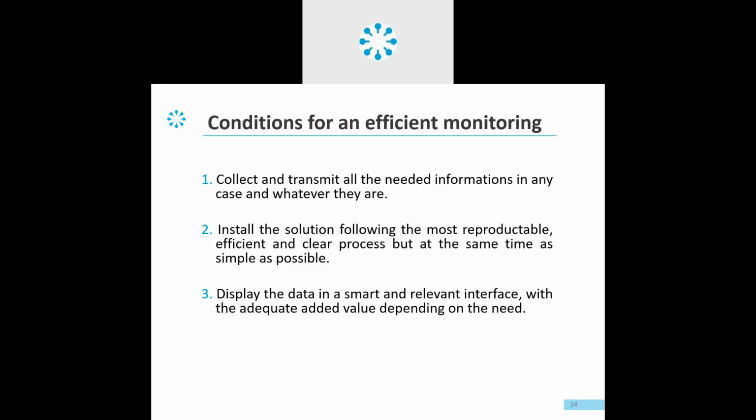This means that your device should be capable of not only reading inverters, but also a number of meters, a number of sensors, your string data, your DG meters, your transformer level information, or whatever field devices you have and you want to monitor. Maybe your dry contacts as well, if your particular circuit breaker is on or if it is tripped.